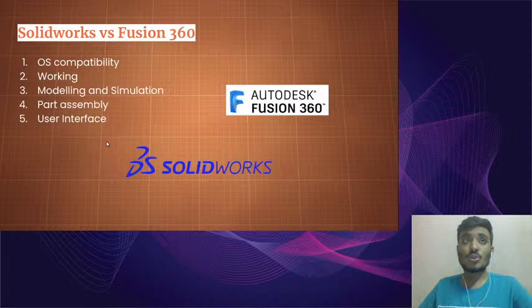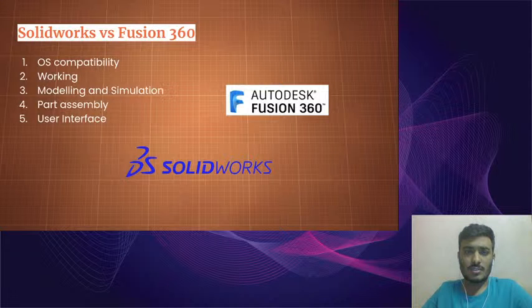Part assembly. A robot might have many parts which require individual design. If we want to assemble them in a single file, then Fusion 360 is your go-to, because in that file you get to save all your work under sub files. All the final assembly will take place under a single file, whereas in SolidWorks it does not happen like that. You need to save individual files for individual parts and then combine them to get a final model. This might not work well when you lose access to a particular file and then have to redesign the model or the component, which takes a lot of time. So that's a minor disadvantage of SolidWorks.